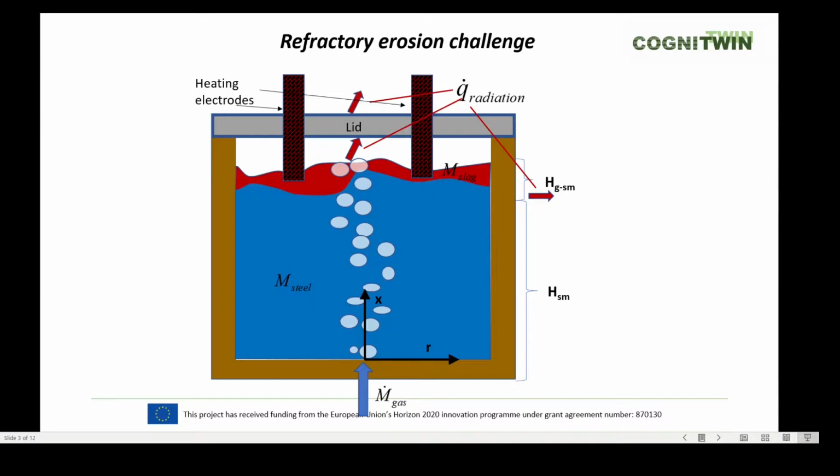We should also mention that there is radiation taking place. Thermal radiation is on the outside to the external surroundings, as well as inside the gas phase in the top of the ladle above the metal. So there will be radiation in multiple directions, equalizing the surface temperatures around in the system.